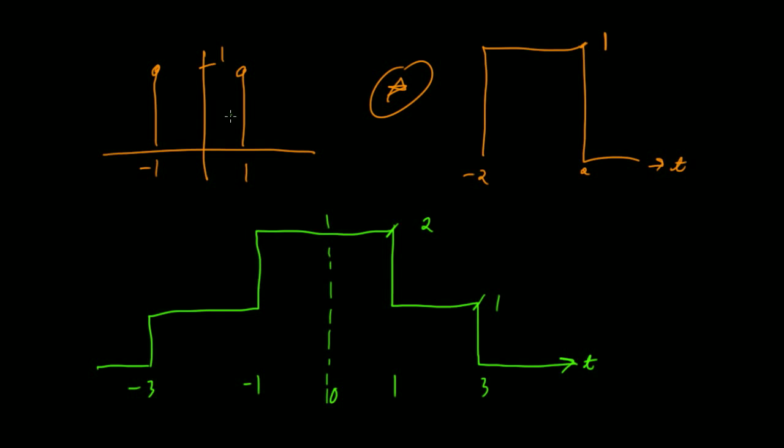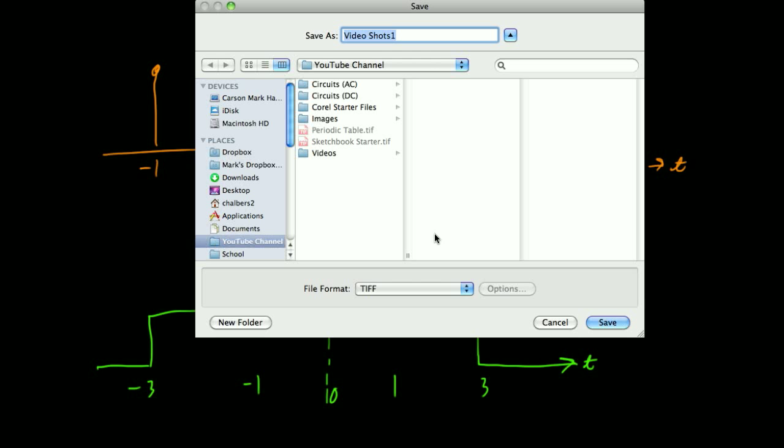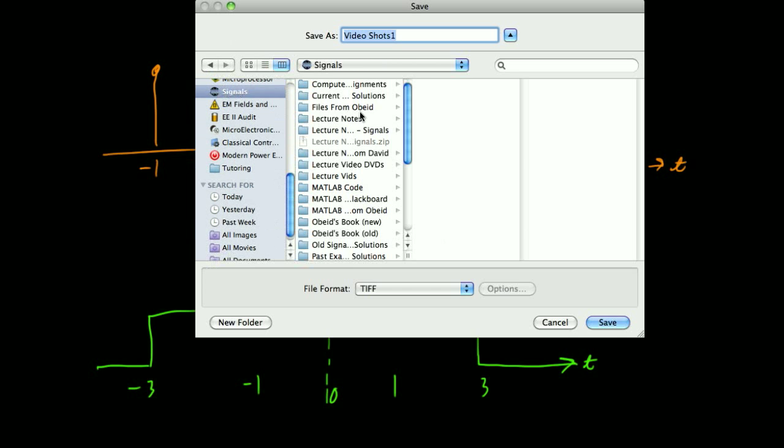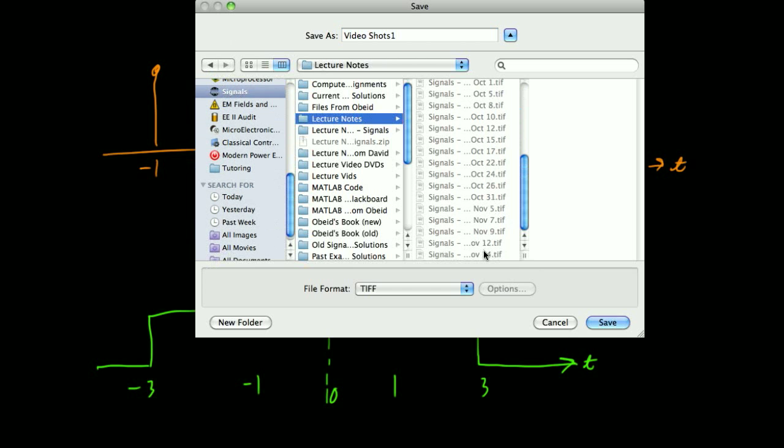If you're multiplying a cosine by a square pulse, then you're convolving their Fourier transforms, which would mean that you're convolving this function with the sinc function, which is why you get two sinc pulses at -1 and +1. But we're just directly convolving these signals, so we didn't get this guy.